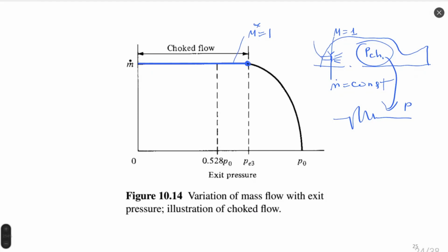If we measure pressure at the same time moment inside our injector, we will see a constant feed pressure inside the line. Even if oscillations happen inside the chamber, they will not reflect on parameters inside the feeding line, the tank, the turbopump, and many